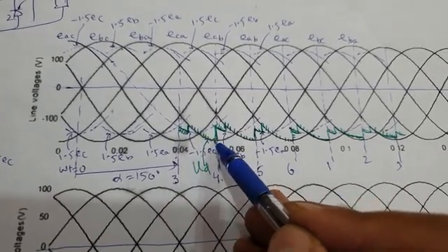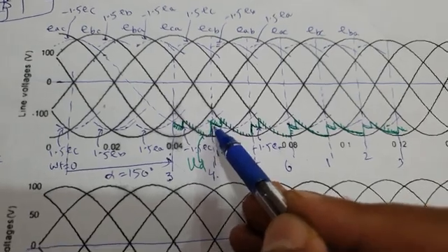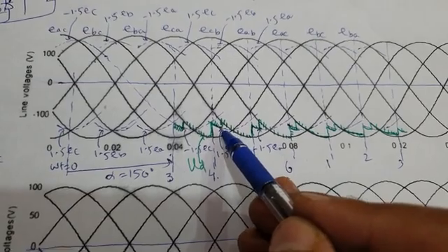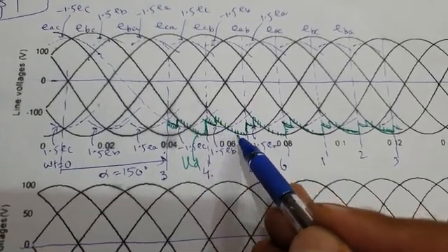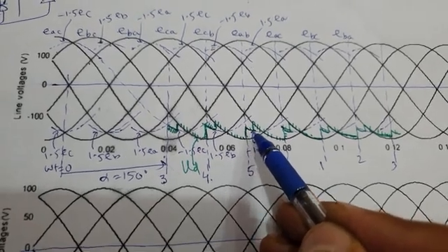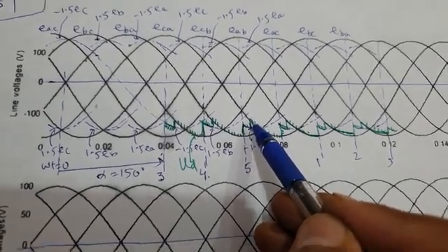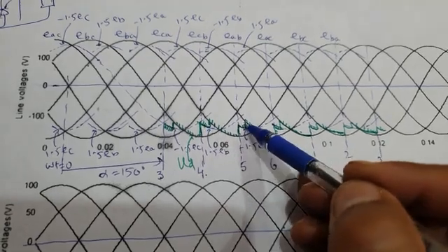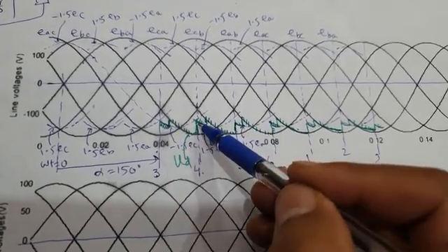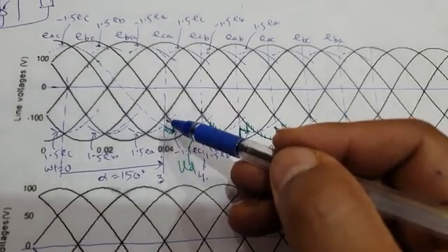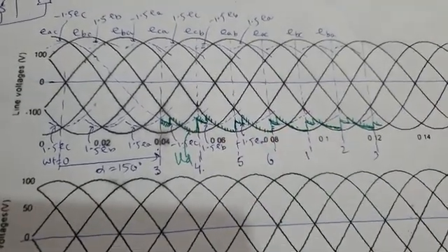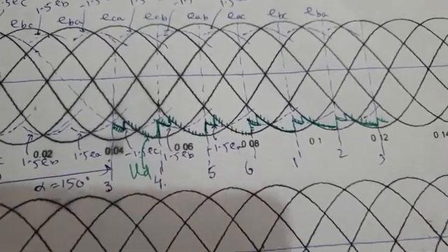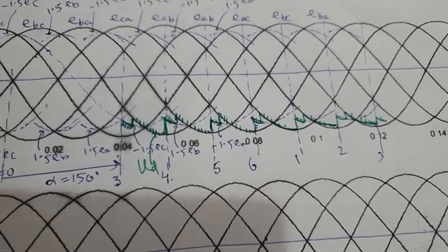Then for 45 degrees, it is line voltage. Then for again 15 degrees, when 3 valve conduction is there, it is again 1.5 times some phase voltage. Then for the remaining 45 degrees, it is line voltage. Then it again drops to 1.5 or minus 1.5 times some phase voltage, then line voltage. So during these 15 degree or U degree intervals, or commutation overlap periods, there is a drop of voltage from line to 1.5 times phase voltage. Therefore, the converter loses voltage. There is loss of voltage. Anyway, this was about phase voltage.